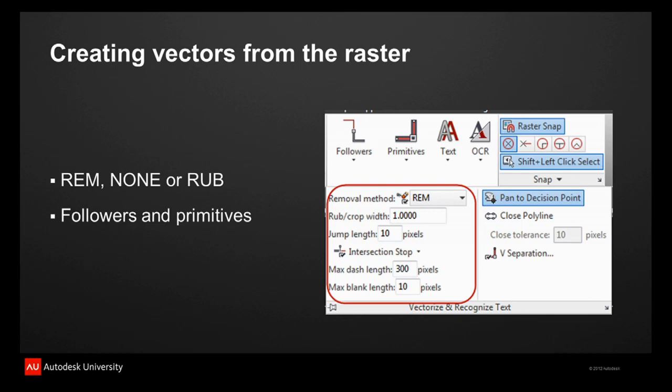All right, sometimes you might have clusters of pixels that are actually still part of one continuous line. So you might have to play around with these settings depending on the quality, again, of the raster image. And if all of this has been set up, and if your raster image was optimized properly, then these functions should work quite perfectly.